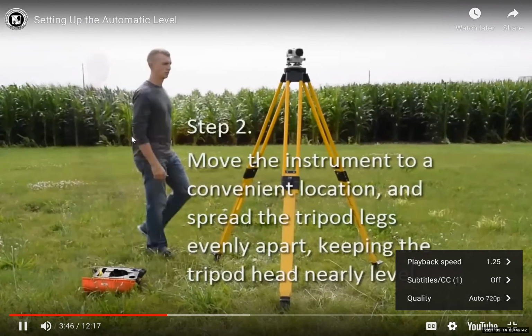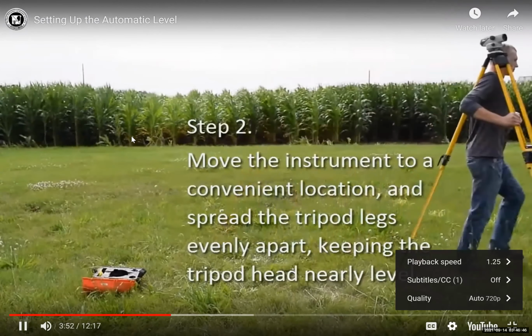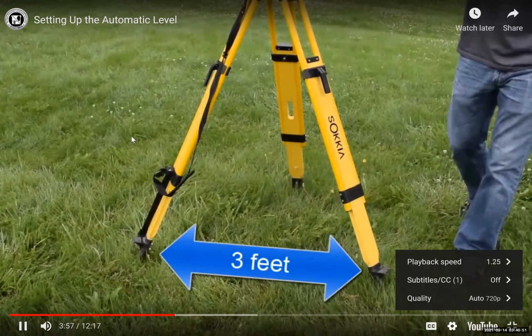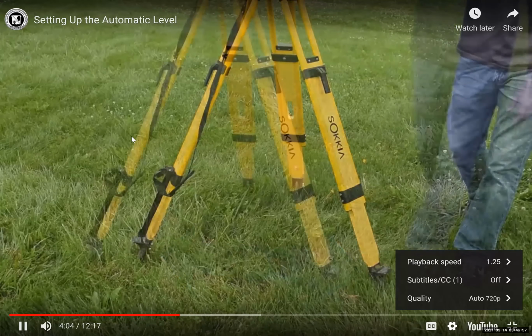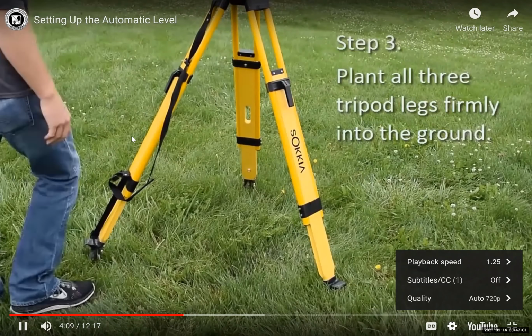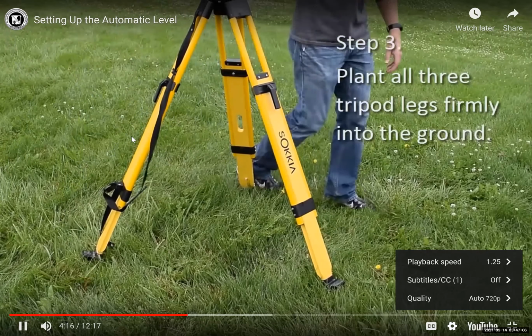When you move the instrument around your project site, carry it in the upright position while still mounted atop the tripod. Spread the tripod feet at least 3 feet apart to make the tripod stable. If they're too close together, the whole thing will be top heavy and unstable. To plant the tripod legs firmly into the ground, apply your full weight to each foot peg. This works on bare earth, grass, concrete, and asphalt surfaces.